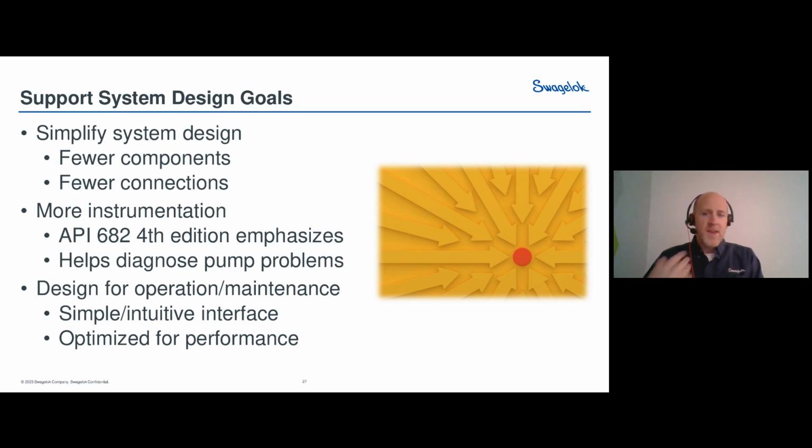Imagine if you had a dashboard, if you will, of instrumentation associated with every pump, where you're seeing the temperature of the seal chamber, you're seeing the temperature of in and outs, you're seeing the pressures in multiple locations, and you know where those things are supposed to be. And at a glance, you could tell if those pressures or temperatures start to change. Maybe we're about to see some sort of a seal issue or a pump problem that we need to address. So it'd be great to have as much instrumentation as possible.